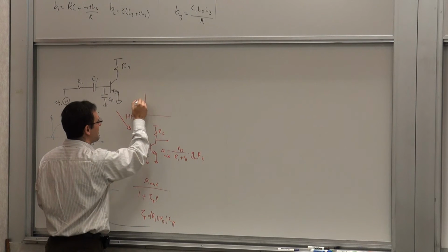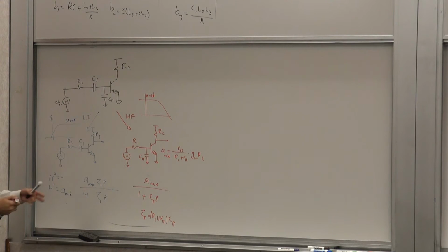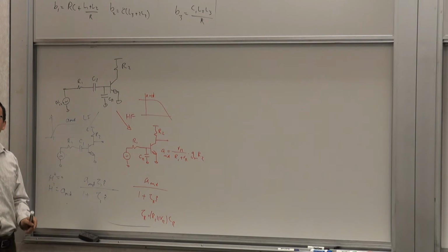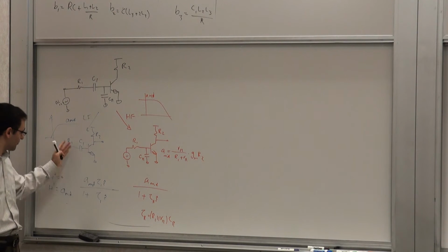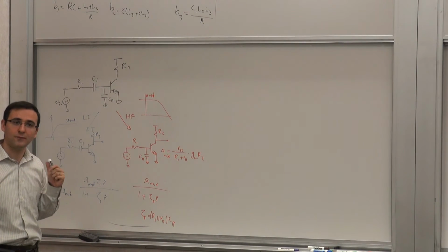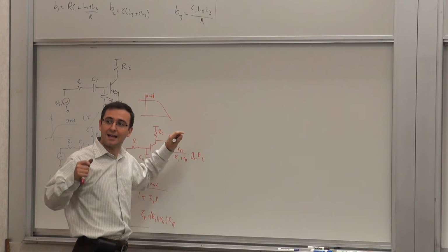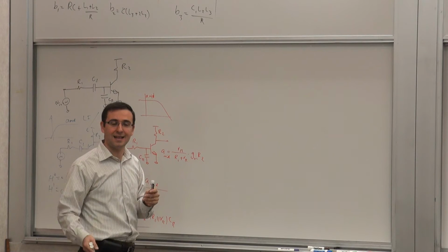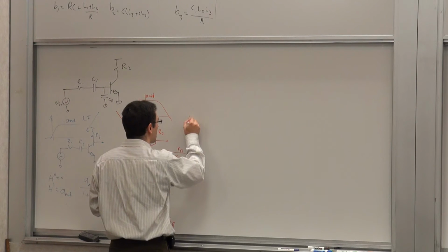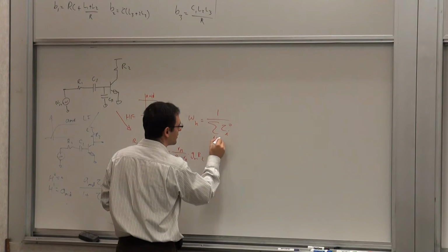Of course, I've simplified it to the minimum required, right? So in this case, I didn't need to really do anything fancy because I only had one capacitor. If I had more capacitors in this equivalent circuit, then I have to calculate their time constants independently to calculate this cutoff frequency. But then I have to, instead of adding the time constants, remember this is different. In the zero value time constant method, we calculated time constants, added them up, and then calculated the 1 over that, right? So the estimate for omega h was 1 over the sum of the zero value time constants.